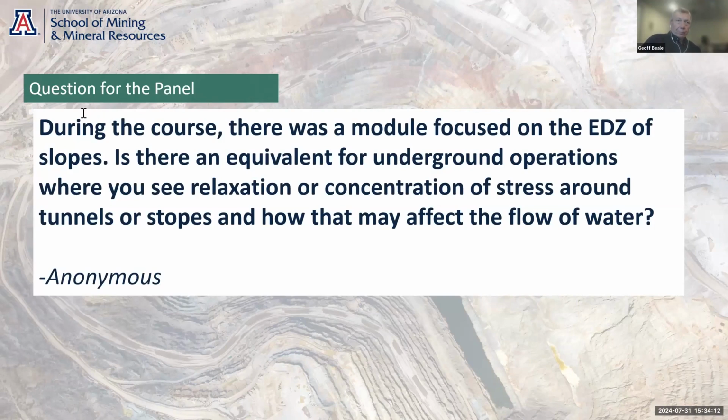And again, an example I've just been looking at this week. We're doing a dewatering system for a stoping operation which has got quite large spans, and which will ultimately be paste filled. And so, you know, we've asked the geotechs to determine what pore pressure they can stand above the spans to still make them stable. And we would then try and put in the dewatering system to achieve those target spans.